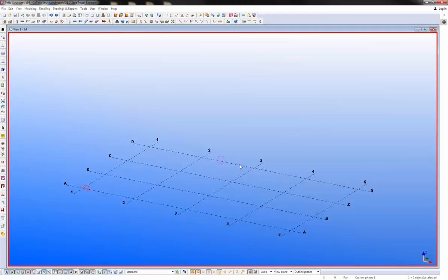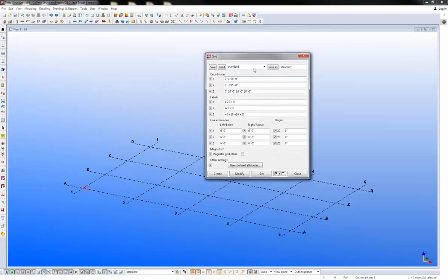First thing I want to do is go ahead and change this grid. So I'm going to set up the grid for each of my levels and also the dimensions of the interior of my stair tower. So very simply, I'll come in here and say that I want spacing at 4 feet, 12 feet 9, and 4 feet. So that's going to basically be my landing width, the spacing between my landings, and then the next